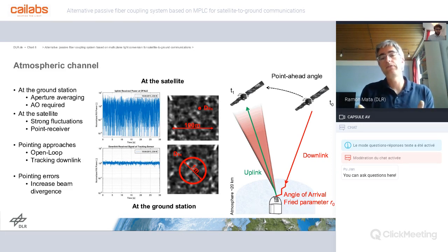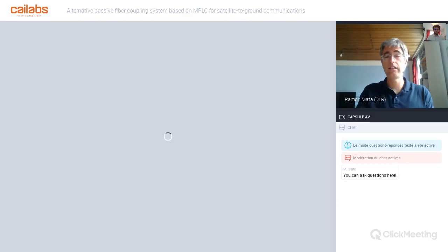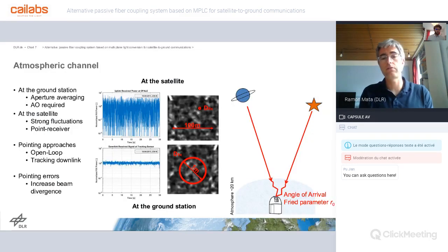That is the effect of the aperture. But on top of that, in downlink, you need to couple the light into the fiber. So if you try to focus this 1 meter collecting light into one point, you will not receive a nice and symmetric point, but you will receive speckles, which depend on the phase distortions on your aperture. So the approach is to correct these phase distortions in a way that we are able to couple it to a single mode fiber. And this problem is similar in some sense to what you see also in astronomy.